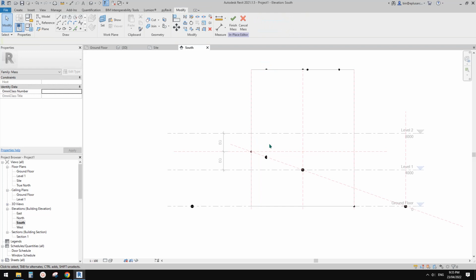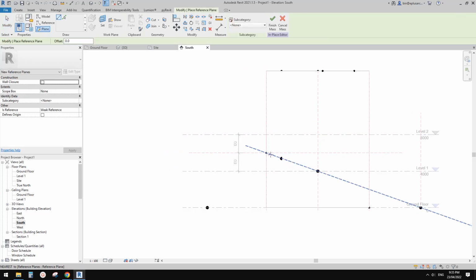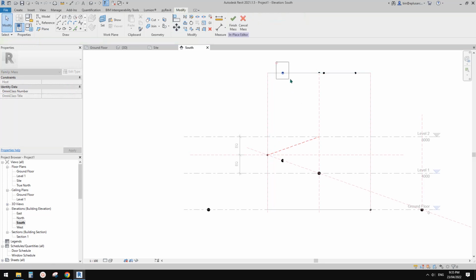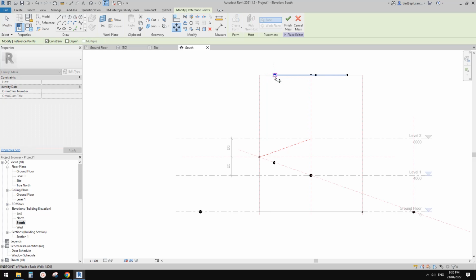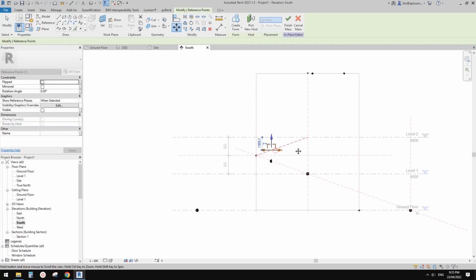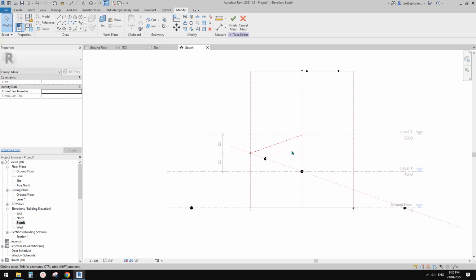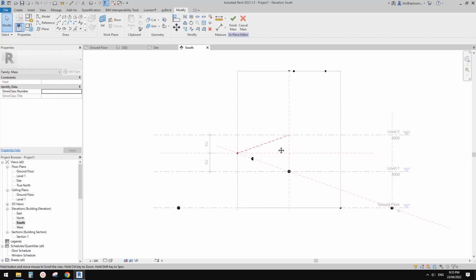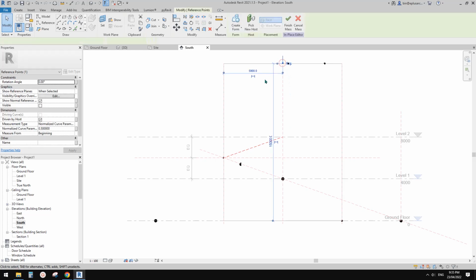Maybe we can create a reference plane in this mess as well. So I'll just create a reference plane here, so I know roughly where it needs to be. Move this unassociated first and move it down to here. We might still need to adjust the height of the point depending on the shape of the spline. Now we need to move this point down.